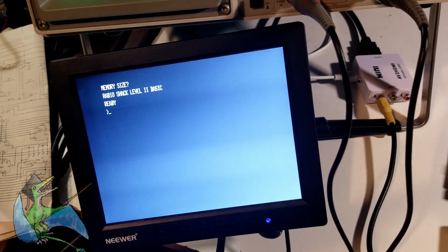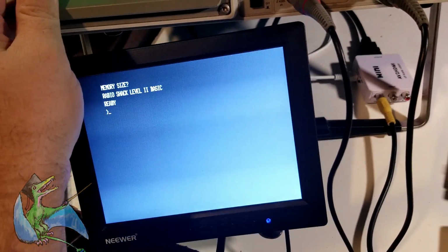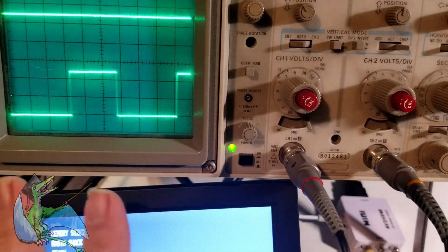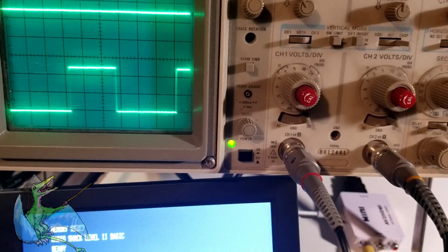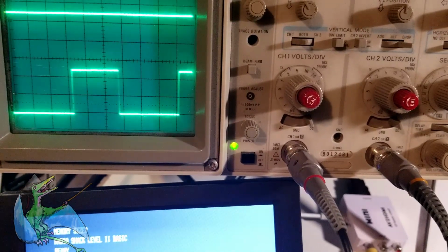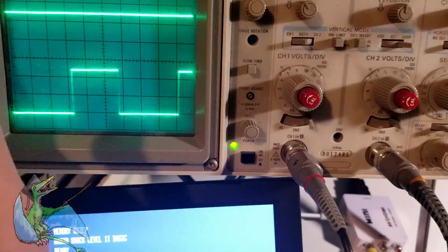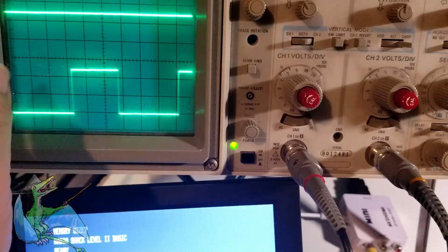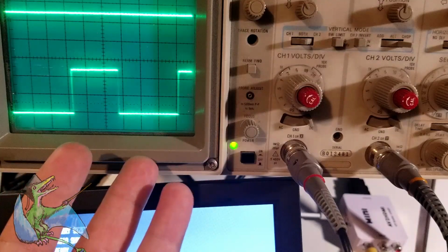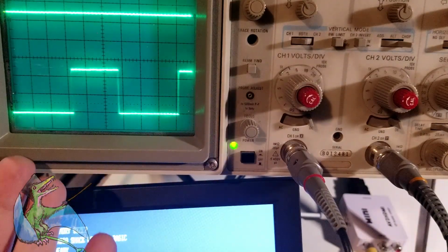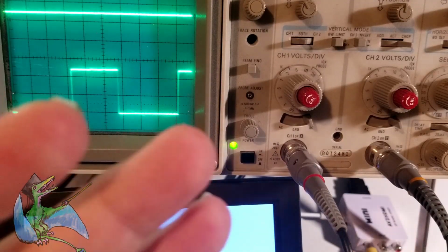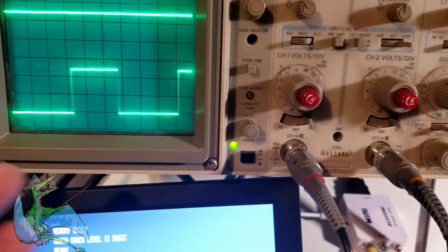I think the big lesson from the last two videos is if you have an oscilloscope, pull that sucker out first thing. I kind of farted around in the first video trying to just shotgun stuff and poke around with the voltmeter. I was thinking that might be more educational because I know scopes are expensive. But I think this shows even a beat up old Tektronix like this, which, if you eBay one of these for less than $100, it's not going to be perfectly tuned anymore. This one's got some inaccuracies.